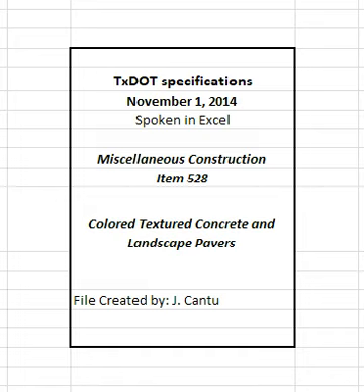3.2.2 Base installation. Perform excavation and embankment work for the subgrade. Replace unsuitable material encountered in the subgrade and compact to a uniform grade. Stabilize subgrade if specified. Place and compact the base to ordinary compaction requirements in accordance with the pertinent item, and to the depth specified on the plans. Grade the base surface so that the finished grade of the pavers meets the requirements shown on the plans.